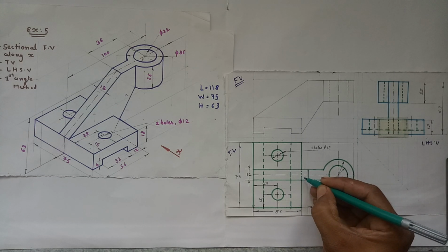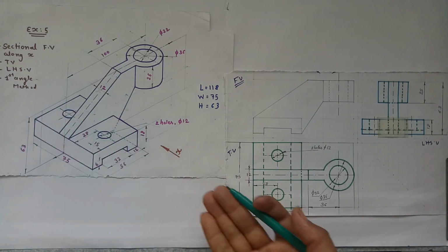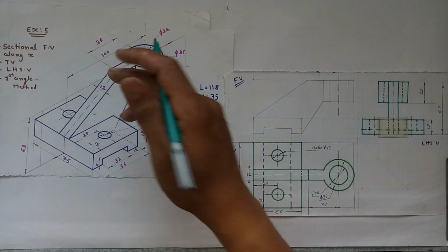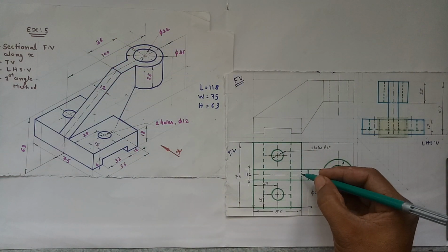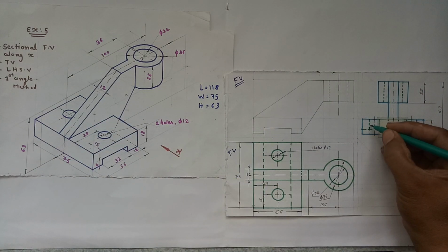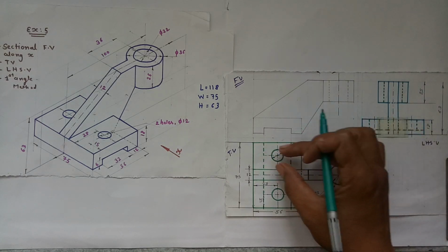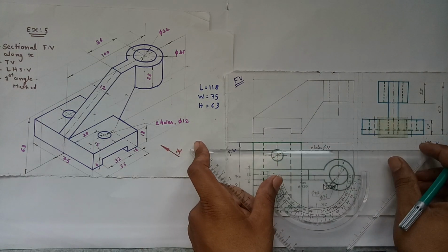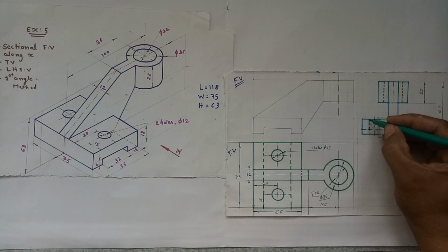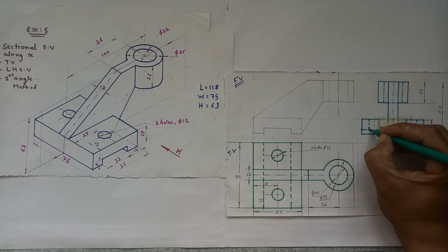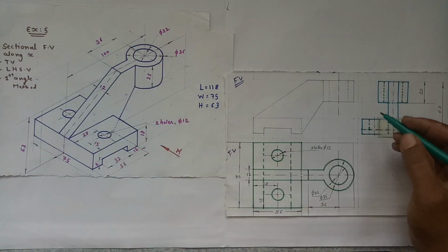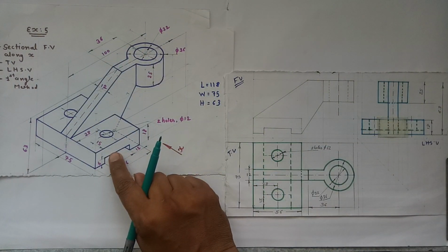Now this hidden line is the hidden outline of this edge, which is from this point to that point, and which is not going to be visible in this particular part. So we have shown the hidden outline for that particular edge. In the left hand side view, here we have shown the hidden outlines of these circles, these two holes, projecting it from the top view over here like this. These hidden lines come up to these particular hidden lines, because the holes are up to the slots only.